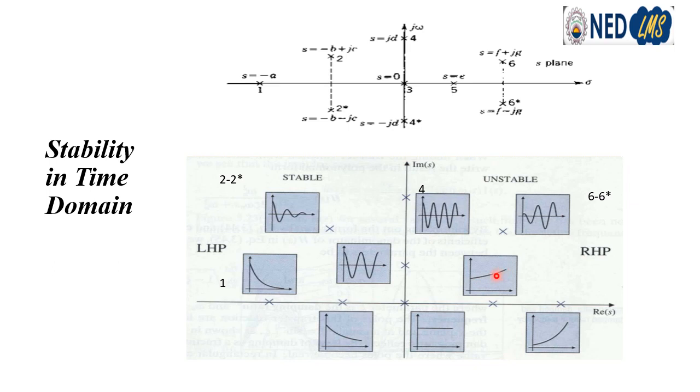Again, we can see here that if it is on the real axis, transients are exponentially increasing. And if it is a complex conjugate pair of poles, that is, it has some imaginary part, then it has some oscillatory part also.